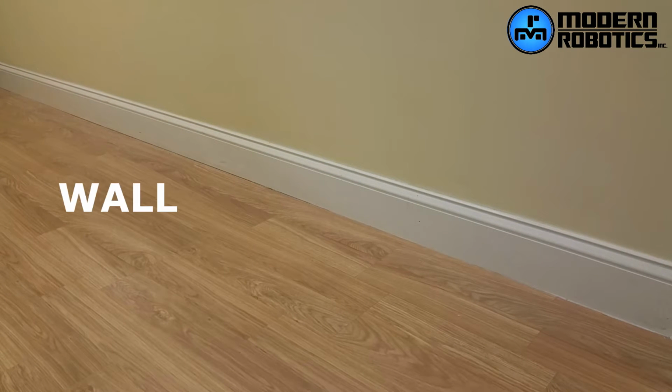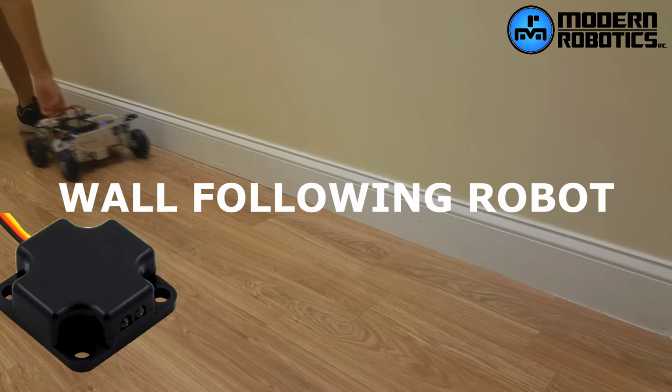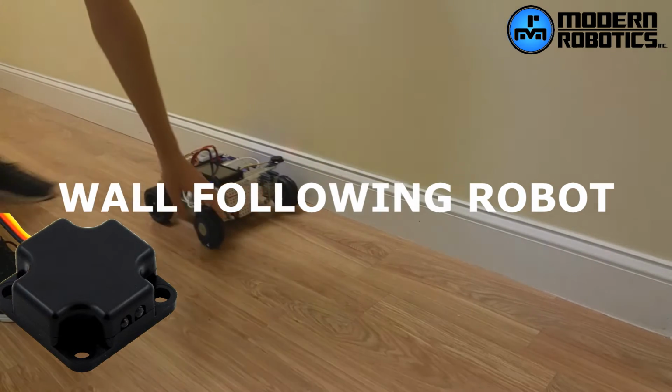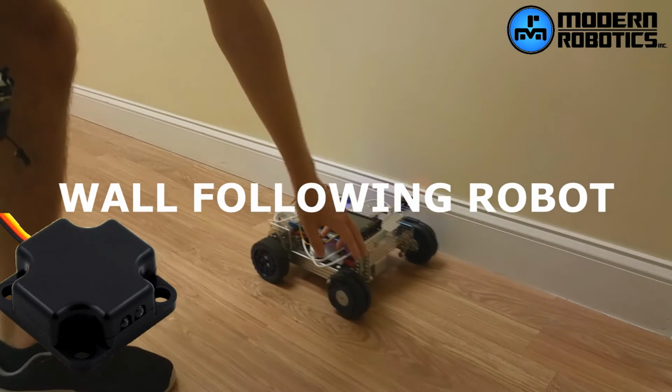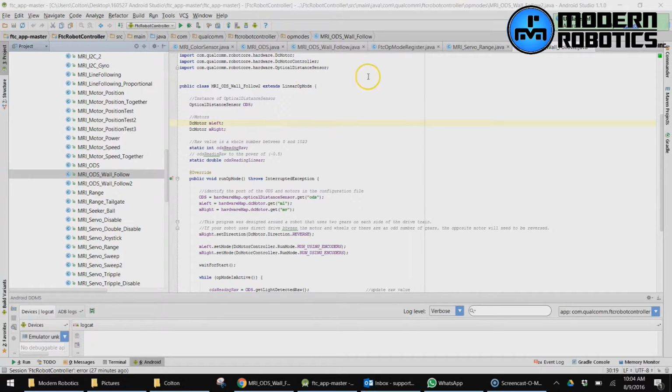We're going to make a wall-following robot using one optical distance sensor and a two-wheeled robot. Those three things only. And then we're going to make a robot that follows a wall just like this one is. If you move it farther away from the wall, it'll correct by driving closer in. If you move it closer to the wall, it's going to correct by moving farther out, and it'll keep this nice straight path down that wall using the readings from the optical distance sensor.